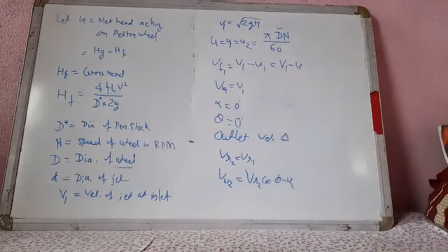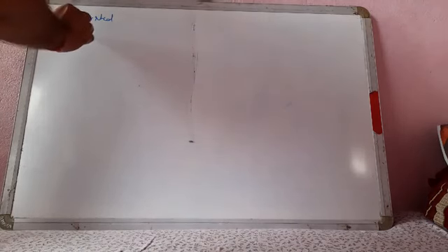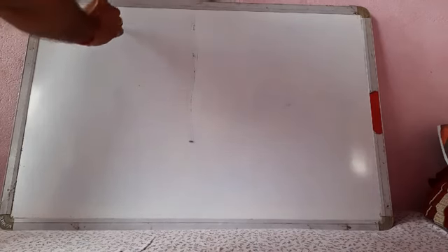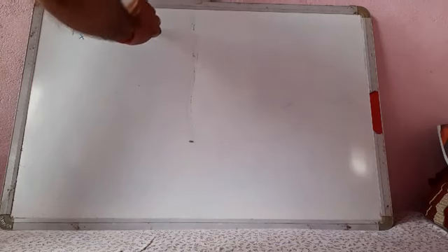These equations we have done earlier also. So the force exerted by the jet of water in the direction of motion, which we have solved earlier in different turbines, is Fx equals rho a V1 into (VW1 plus VW2).